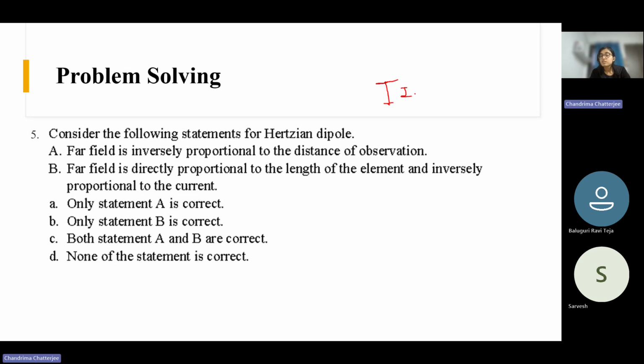This is very small, and this could be the smallest unit which can radiate, which can cause radiated emission. This is the smallest unit you can imagine. So this is a dipole. And due to this, we have to calculate what is the radiated emission at a particular distance.